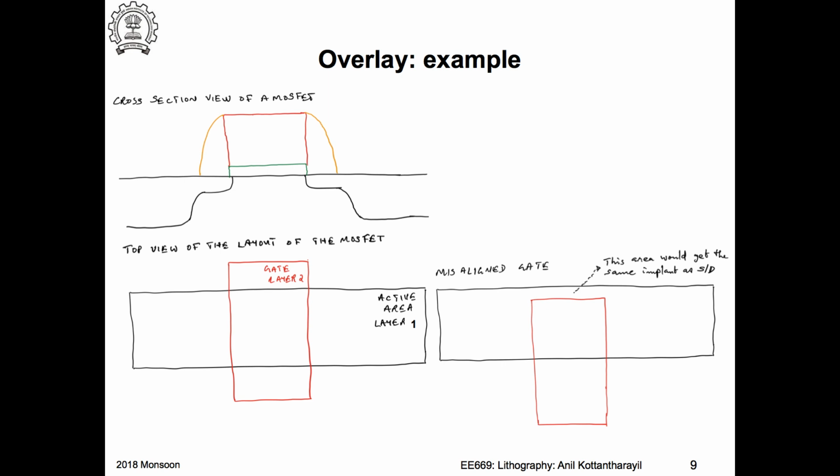But when I was doing my M.Tech, for example, this was the end of the story for a VLSI designer. You make the layout, so you have this nice circuit that you have designed, and you do the simulations using SPICE and make sure that it works and meets the specifications, and then you create the layouts.